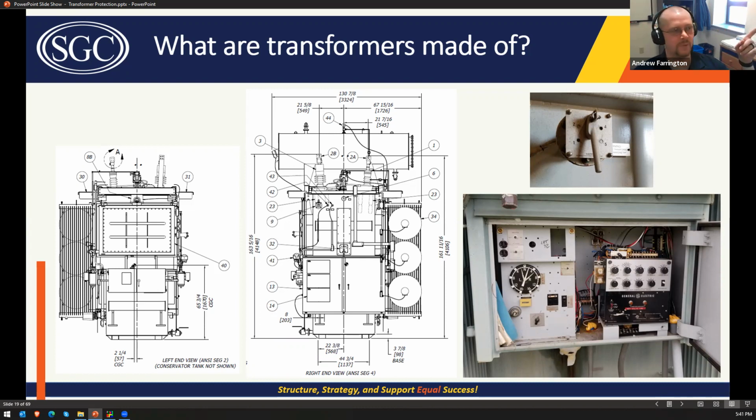So the line drop compensation will take the current that is going through the transformer, and you can input the impedance of the distribution circuit, and the LTC controller will calculate what the resulting voltage will be at the customer. And then you can bump this up to whatever, 125 volts, such that when it gets to the customer, it's 120 volts. This is all stuff I run into all the time, and I'm assuming many of you will too.